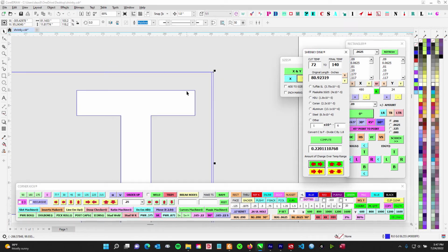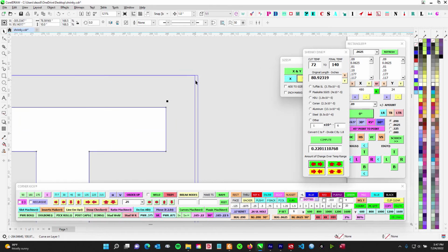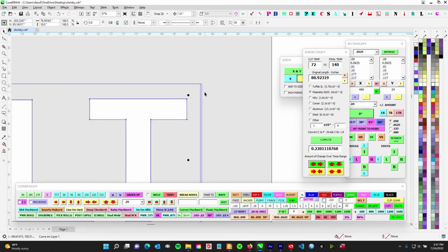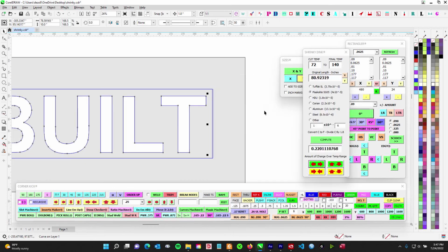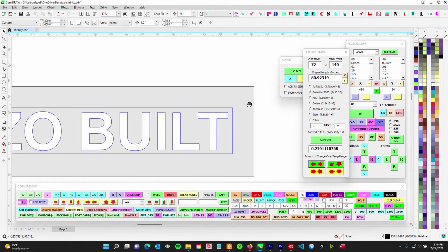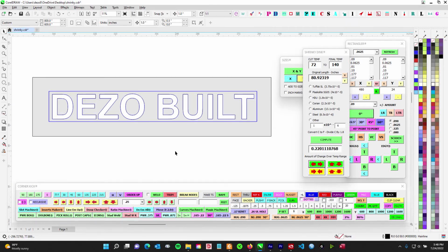What happens is you have these letters that are trapped by the aluminum face that doesn't grow nearly as much. And essentially those letters are in shear their whole life. That glue is trying to hold back the rain. You're welcome. It's in your mind now. It's trying to hold back the rain. And it's fighting. And so we had the problem. The customer called us and the letters were falling off.